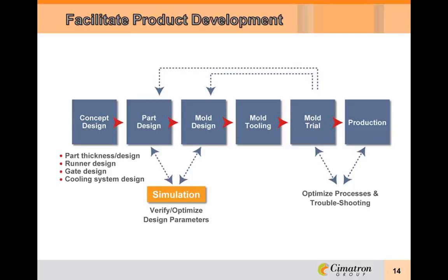In this way, mold construction has not begun until the molding trials on the computer meet the requirements. The interrelation of part design, material selection, part performance, and processing is all taken into account. Modification of part design and mold design is flexible and concurrent.